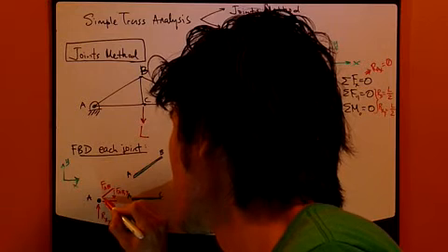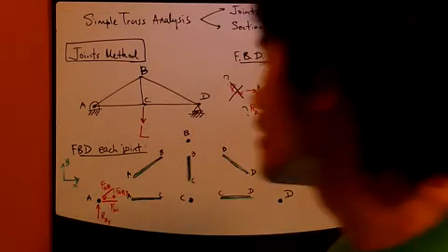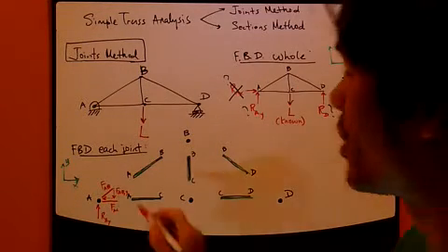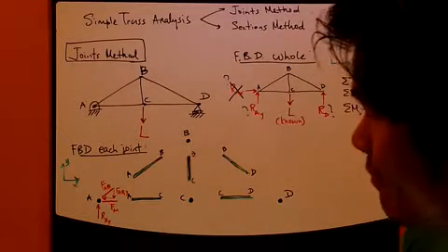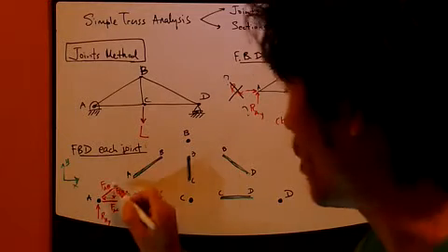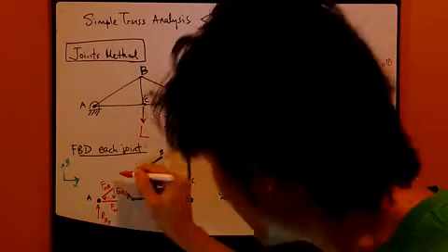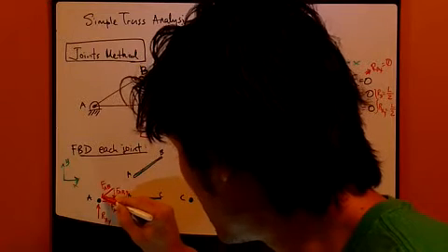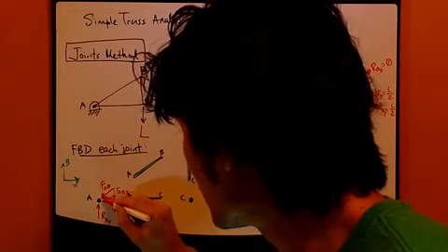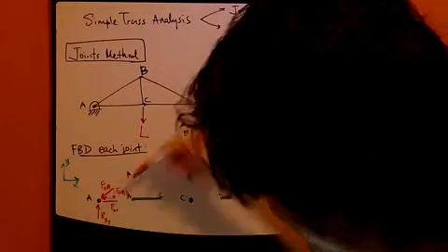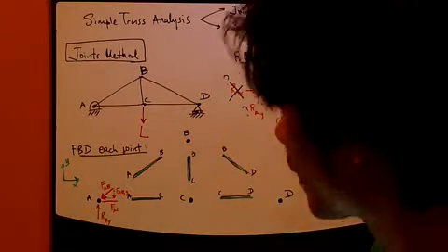The X component must point to the left. And knowing the components' directions, immediately you know the FAB direction, which must follow the direction of the components. So FAB points downward into the joint.